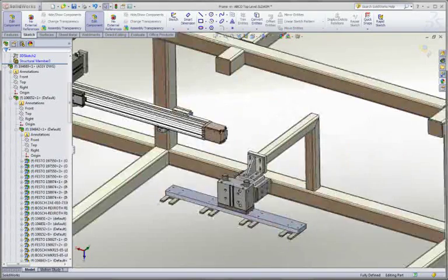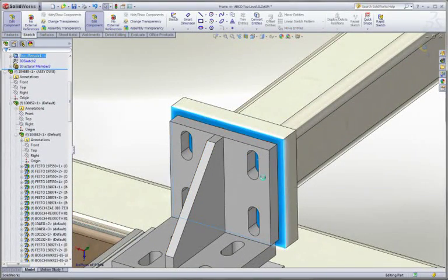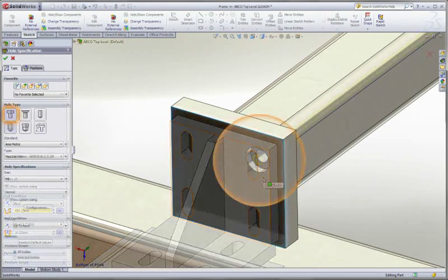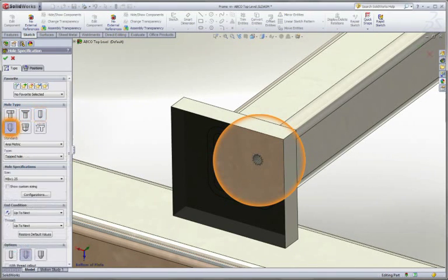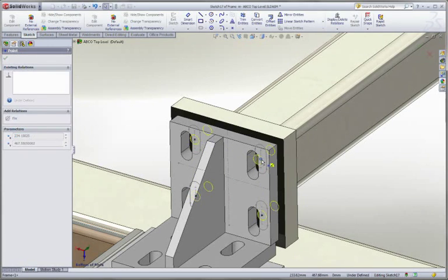To ensure these components bolt together, we're going to use SOLIDWORKS' powerful Hole Wizard. This tool is the all-in-one solution for fastened connections, providing a variety of hole types, such as counterbored, countersunk, drilled, tapped, and many others. If you've ever had issues with misaligned holes during assembly on the shop floor, you'll love that SOLIDWORKS allows you to easily reference other components here as well.